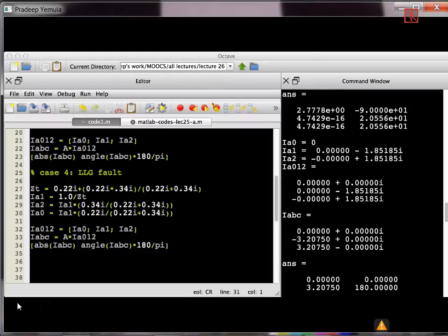So what is the purpose of doing all these calculations? You know what is the fault current, you can expect this much fault current is going to come in the network. So based on that you can design the relays, you can design the circuit breakers, how much relay setting for fault current, all that things you can manage. How to limit the fault current? So by increasing the neutral impedance, I can limit the fault current. So if I want to limit this current to only 15,000 amperes, what should be the Zn? You can do that reverse calculation also.